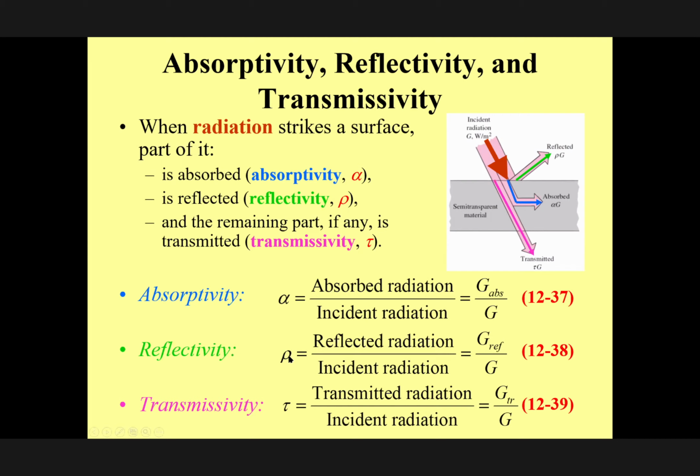Cool material absorbs a minimum amount of radiation and reflects most of it. Therefore, they are now using white color to paint the building, to reflect maximum energy to the outside. It doesn't absorb energy in the community, okay? We call it cool material because those materials have high reflectivity and reflect radiation back to the sky. These are things we have to pay attention to. This is called cool material. If you just Google cool material, you can see materials with high reflectivity that reflect back maximum radiation.